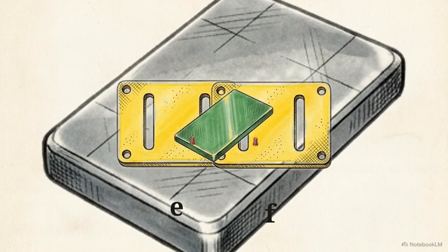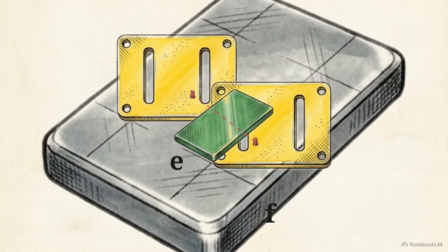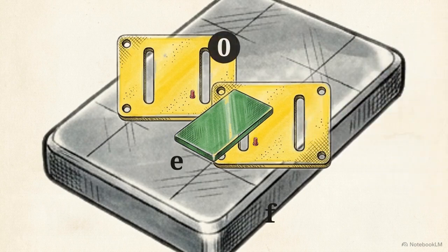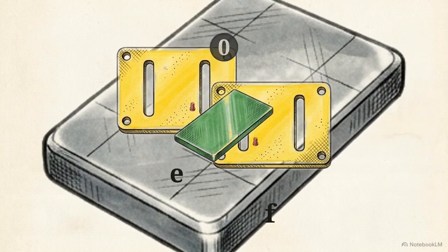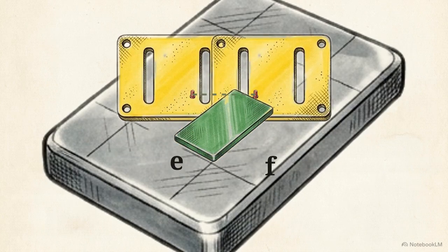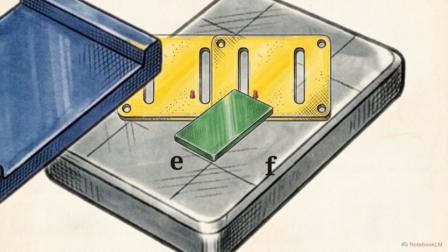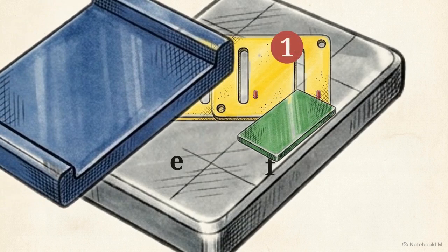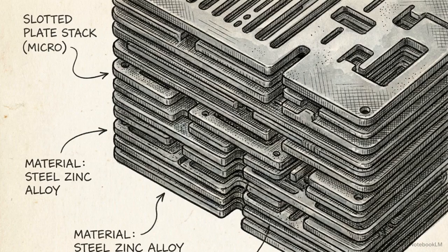To bridge these distinct inputs, Zuse introduced an intermediate floating plate, locked into the assembly by 2 independent switching pins. If only one input moves, the geometry fails to catch the horizontal clock pulse. Only when both plates move vertically do the pins align perfectly, catching the pulse and driving the output plate forward. By layering floating plates and slotted pins, Zuse achieved Turing-complete logical operations strictly through geometry.